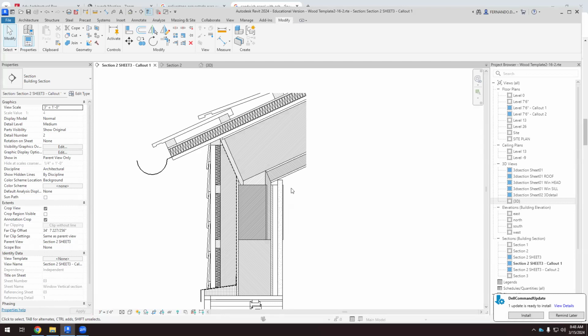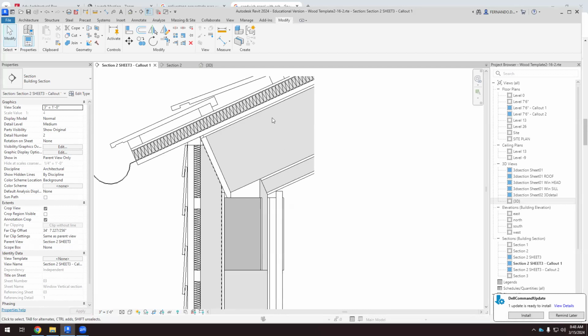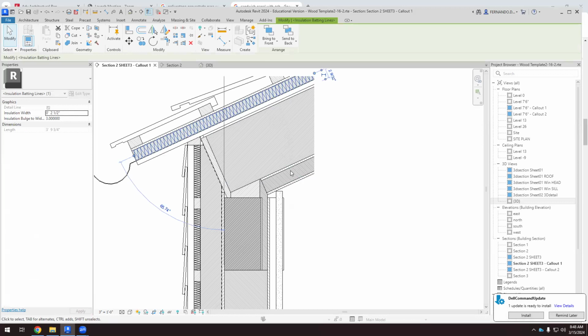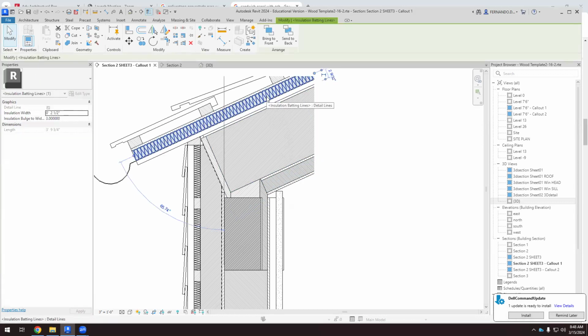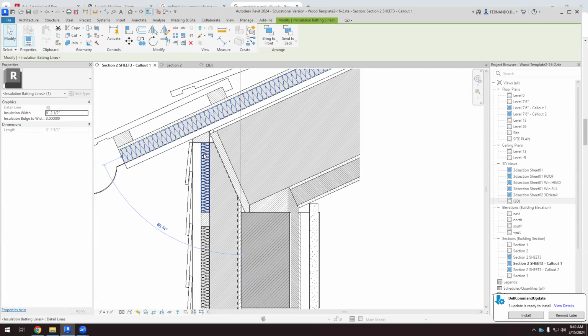Okay, so I think now we are done. We have more thermal insulation probably than we need. Well, it doesn't do any harm. It's more expensive having thermal insulation outdoors and indoors. But what we have to understand is that the outdoor thermal insulation, especially if it's in the roof, I wouldn't use cellulose. I would use this rigid thermal insulation because it's more reliable, and if it gets wet, it's not affected by the moisture or the water. So that's why we have this here and this there.